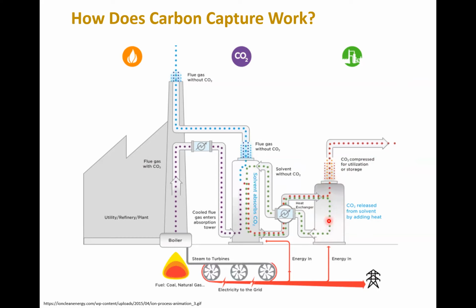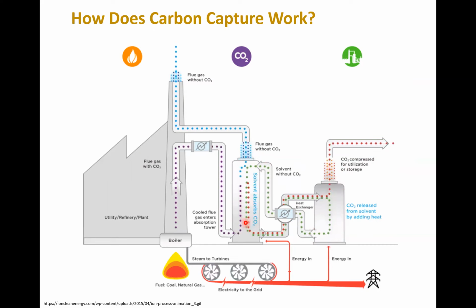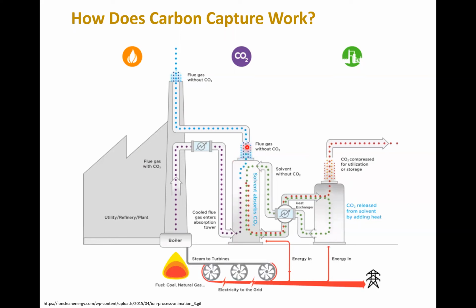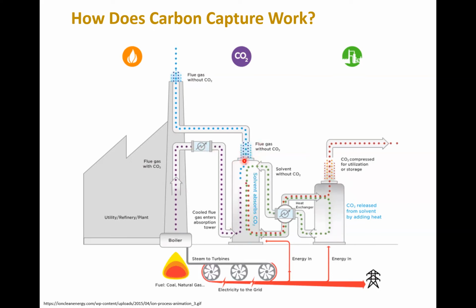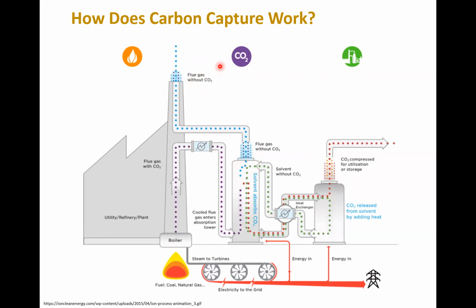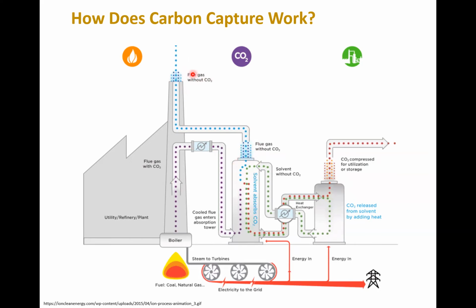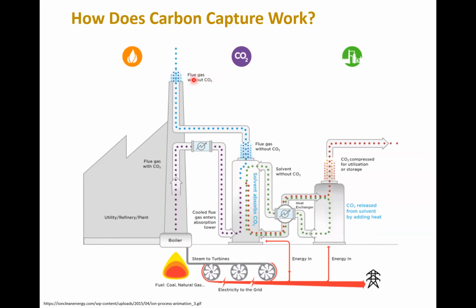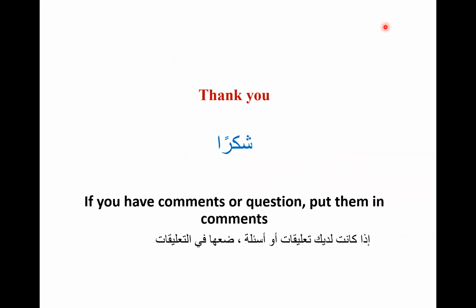The recovered chemical, which is monoethanol amine, can go back to the absorption tower. Of course, as we mentioned, maybe the efficiency is 90%. So some of the carbon dioxide may also go through the flue gas and end up in the atmosphere. So this here is flue gas without carbon dioxide, but depending on the efficiency, how much you get, it may not be completely free of carbon dioxide and can still contain some. With that, I hope this is useful, and see you next time.